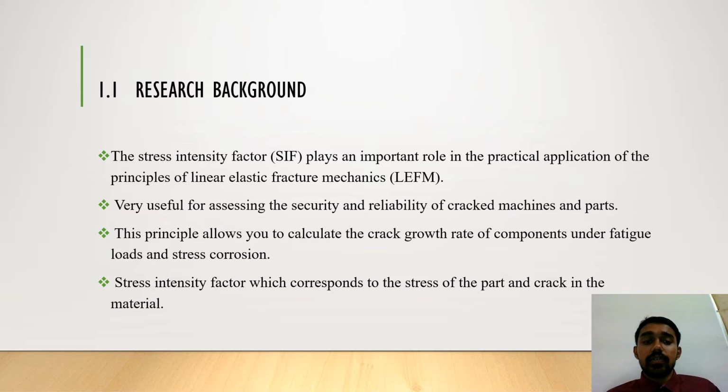The stress intensity factor is very useful for assessing the security and the reliability of cracked machines and parts. This principle allows you to calculate the crack growth rate of components under fatigue loads and stress corrosion. The stress intensity factor corresponds to the stress of the part and the crack in the material.